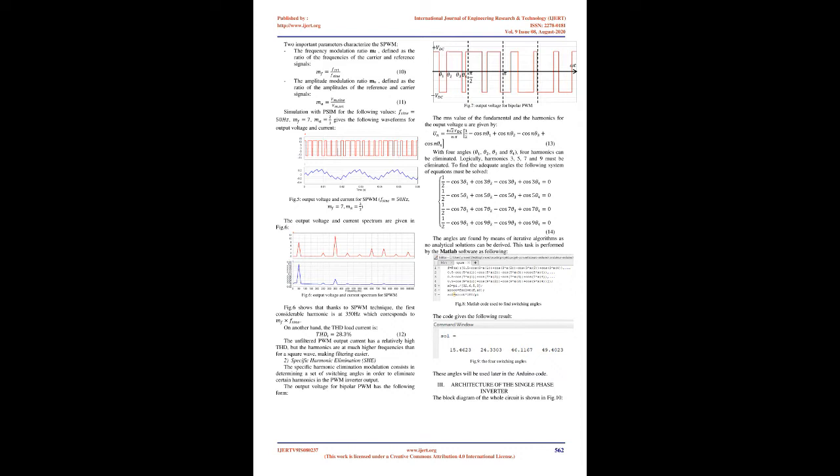The quality of a non-sinusoidal wave can be expressed in terms of total harmonic distortion, THD. The closer the waveform is to sinusoidal, the smaller the THD. For a square wave inverter with VDC equals 12V, R equals 25, L equals 100 mH, F equals 400 Hz, the THD of the output voltage and the THD of the load current are respectively.